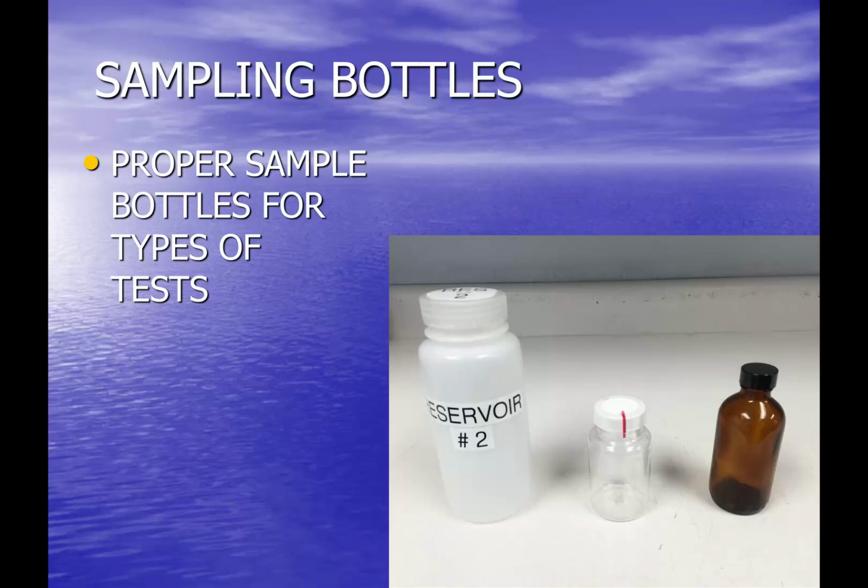Those are the primary vessels we use to test for the microbiological safety of our drinking water, for total coliform rule compliance. That comes from that 100 milliliter bottle. The one on the right is a 250 milliliter bottle that we use for disinfection byproduct testing.